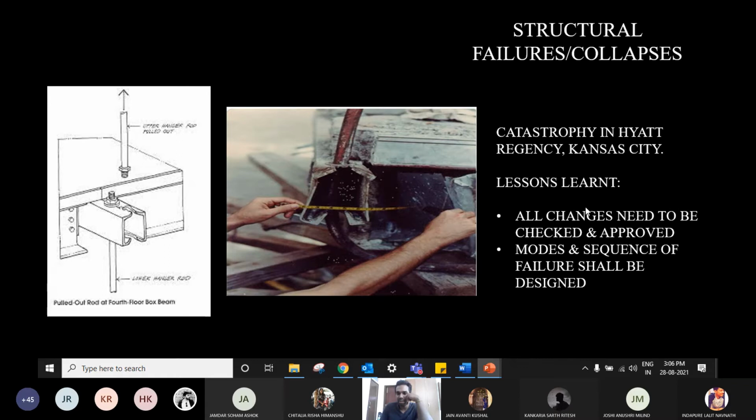So the big lesson that we learn is the design drawings. Once the shop drawings are made out of the design drawings by the fabricator or the contractor, it needs to be verified. So guys, if you're in a position somewhere and you're seeing somebody is actually creating a shop drawing which is based on the design drawings, check if it's verified or not by the original designer.